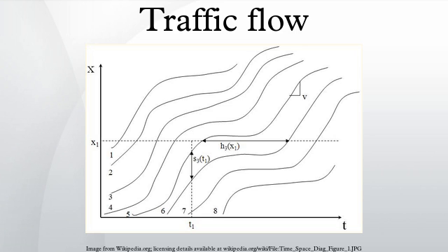After generation, it makes the different origin-destination pairs between the locations found in step 1. Modal split, mode choice: the system has to decide what percentage of the population would be split between the different modes of available transport, for example cars, buses, rails, etc. Route assignment: finally, routes are assigned to the vehicles based on minimum criterion rules. This cycle is repeated until the solution converges.